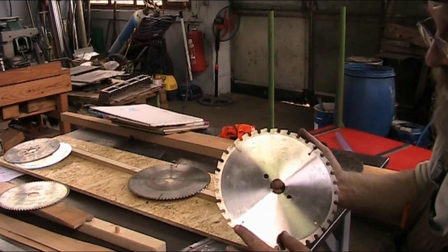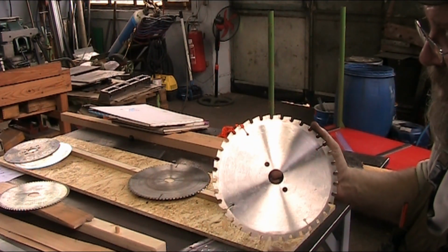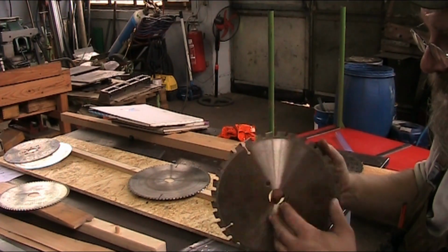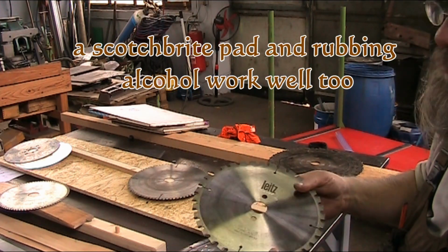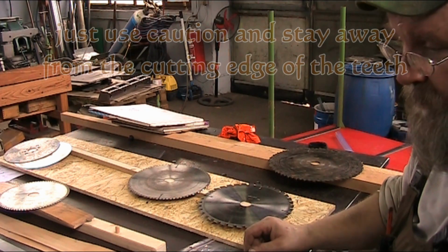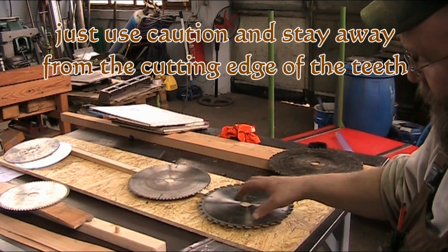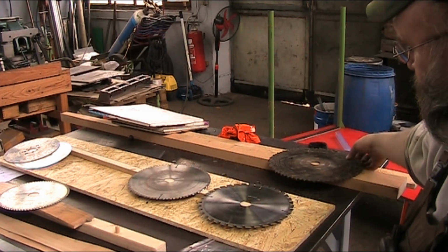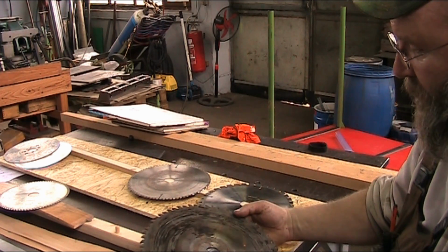And as the blade gets hot, it'll accumulate pitch behind the tooth. You'll see that in some of your cuts, I'm sure. And so you're going to be out there cleaning your blade. If you clean your blade, use a brass bristled brush and not a steel wire bristle, so that way you don't dull the edge of your teeth when you're cleaning your blade. But anyway, back to the normal wood saw.